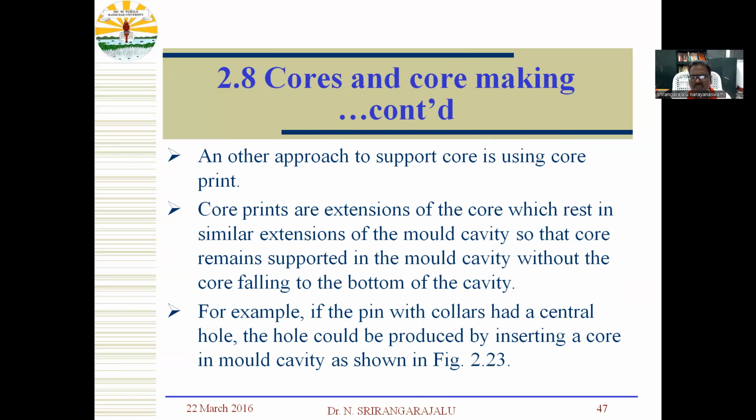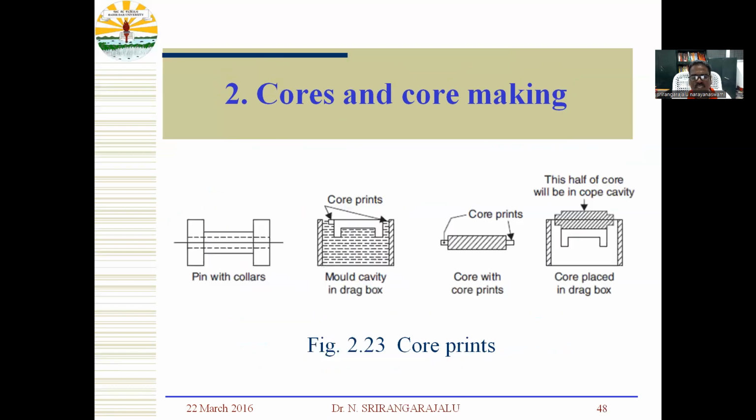For example, if the pin with collars had a central hole, the hole could be produced by inserting a core in the mold cavity, as shown in figure 2.23 here. Okay, pin with collars, and these are the core prints. Core prints are provided, and then if core prints are like that, we can fix it.